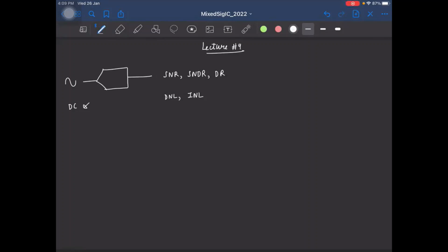So there is one last thing I would like to add to this part, which is the following. If you take INL, how you find INL is that we take the input voltage, sweep it to all possible values, and record the output, right?